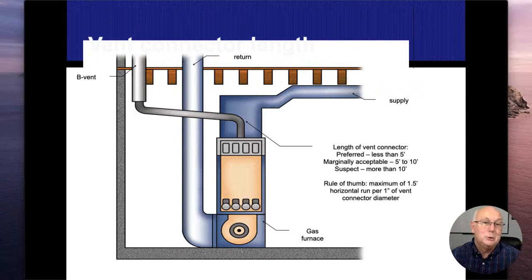So now their solution is either to build a fireplace with a secondary flue going to the outside, or they can go ahead with a higher efficient water heater and just direct vent it straight out the sidewall. And I believe that's the route they're going. So they're going to disconnect it from the chimney and then put that sidewall in there.